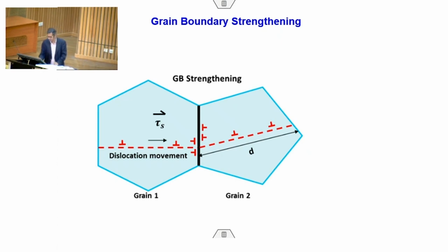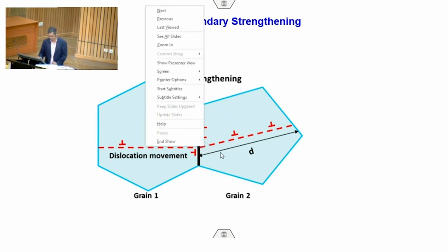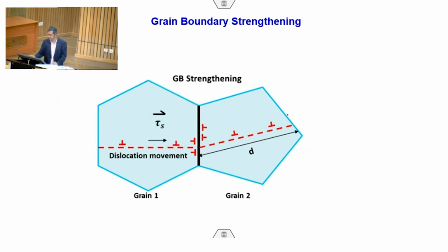See, this is a two grain model. You can see this is the plane, slip plane. Dislocations are moving like this, and then reach the grain boundary and pile up. Correct? So, in order to start the dislocation motion in the other grain, enough stress should be applied so that the other grain starts deforming and dislocations start moving. Or it should be that the two grains have the same kind of slip planes at a certain deviation from the angle.